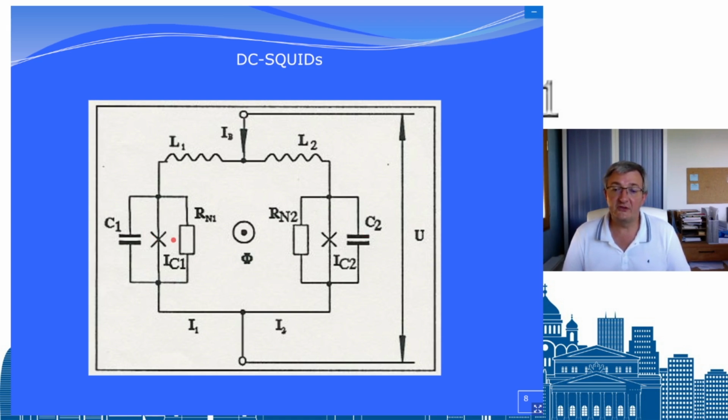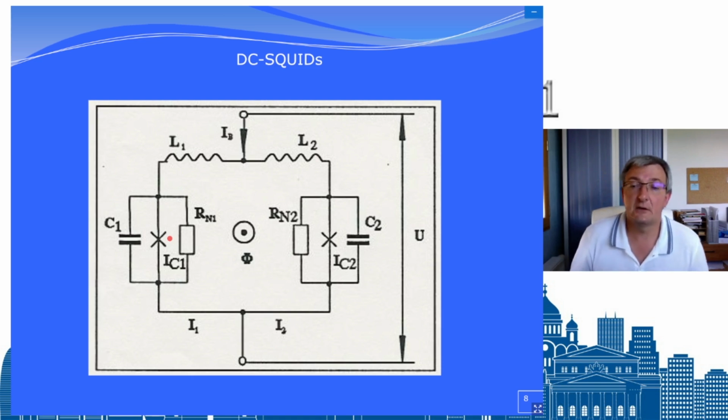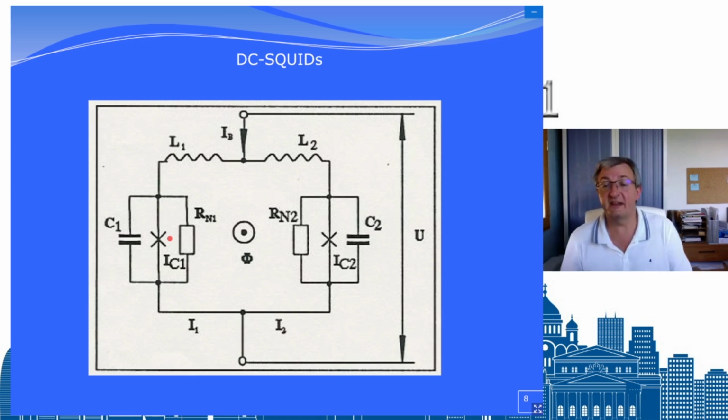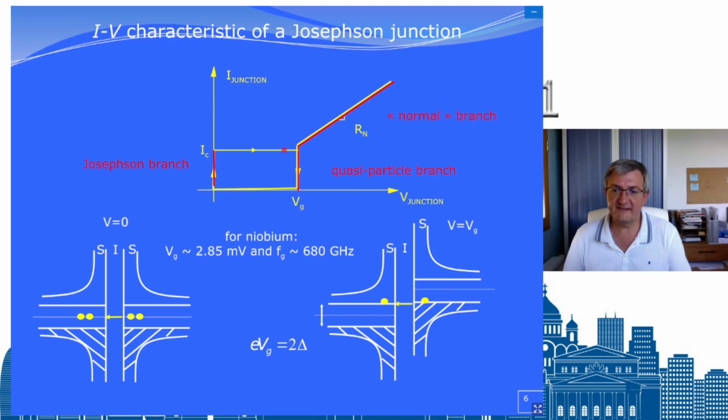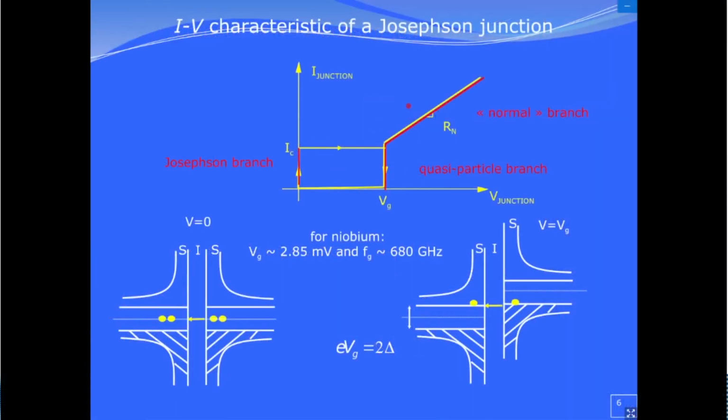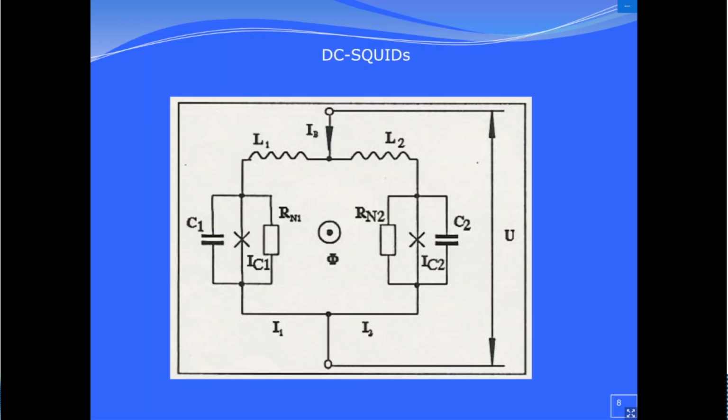And we also put in this normal resistance, because even if you don't want it, there are some quasi-particles, and at some point, when you put too much current, you will have a resistance. So the current will go through this resistance. It corresponds to this part that you see. A simple model says that this resistance is constant, but there are more evolved models where the resistance is nonlinear versus voltage. You can put that in this electrical model with an arrow here, you put it nonlinear to take into account a little better the properties of